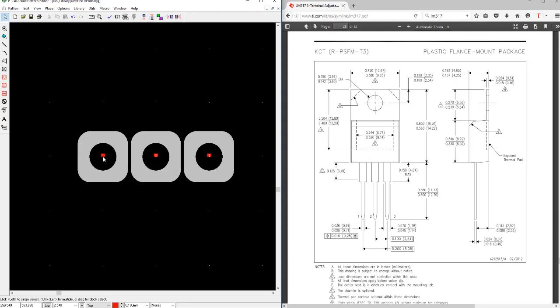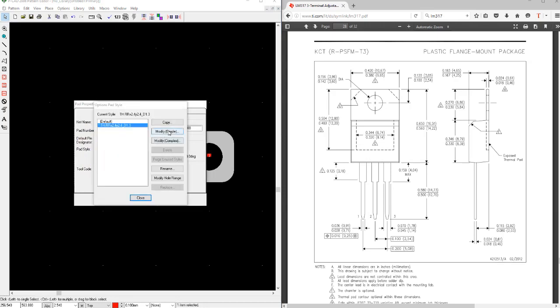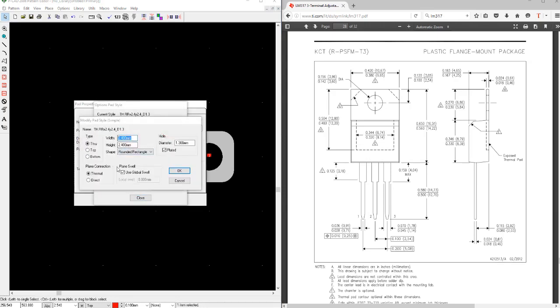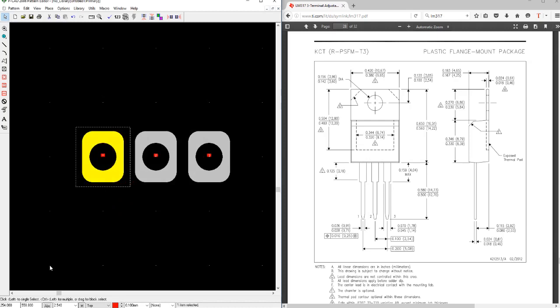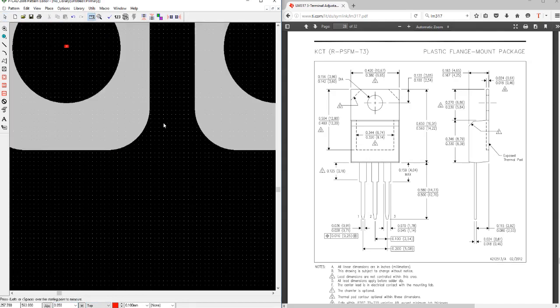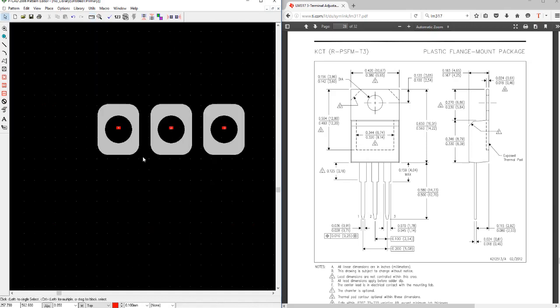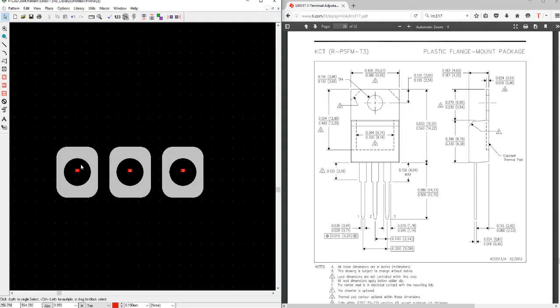You're going to probably get solder bridges, so there I want to basically reduce the pad size ever so slightly. So we go modify simple, and we make this 2mm. So we only make the width 2mm. I just want to basically go and make this grid 0.05 at this point in time so that I can nicely measure it. So let's go and quickly measure between this point and this point, and we see here from the bottom we have a clearance of 0.5 millimeters. 0.5 millimeters is acceptable for normal hand soldering, so we can use that.